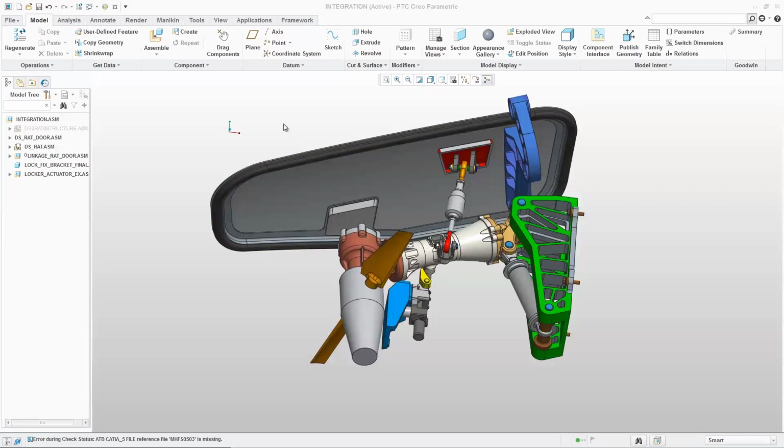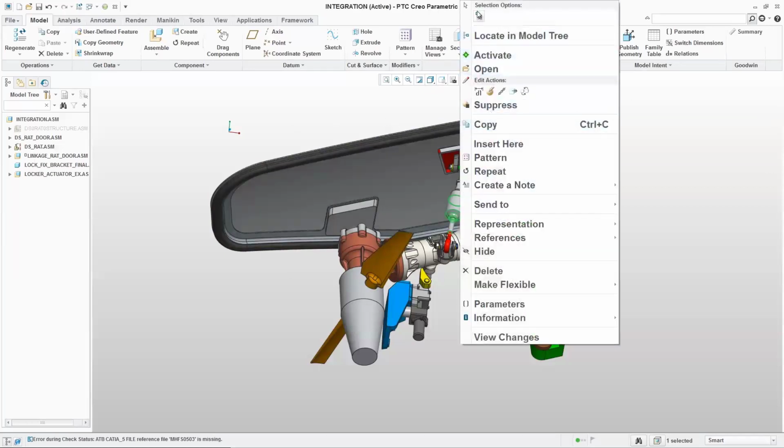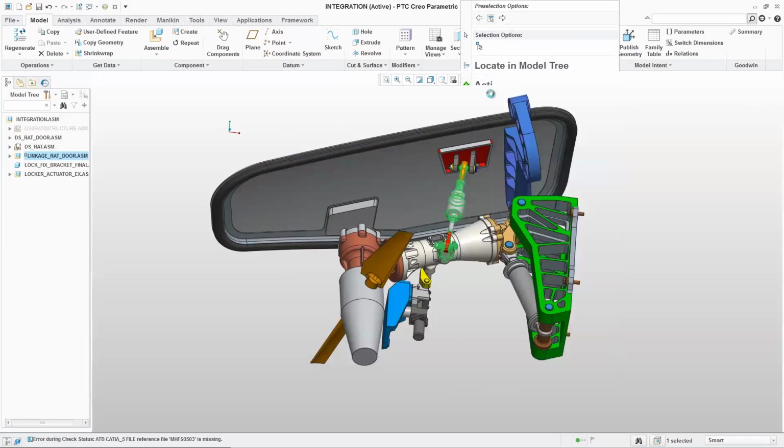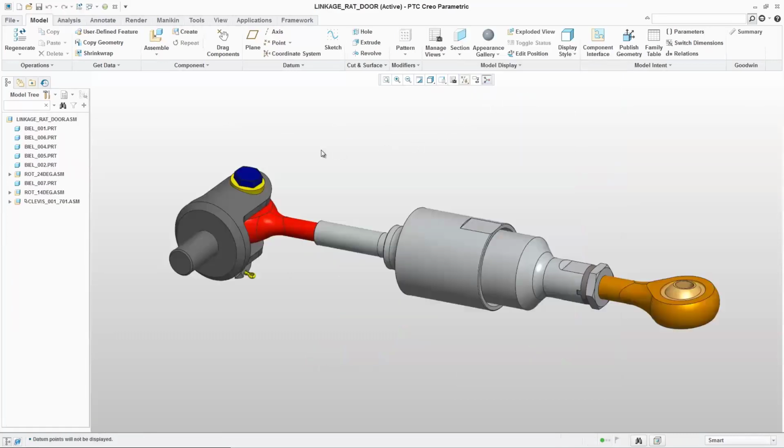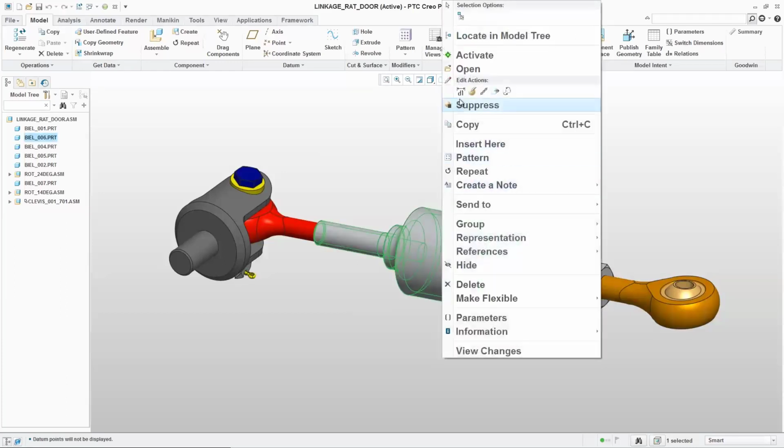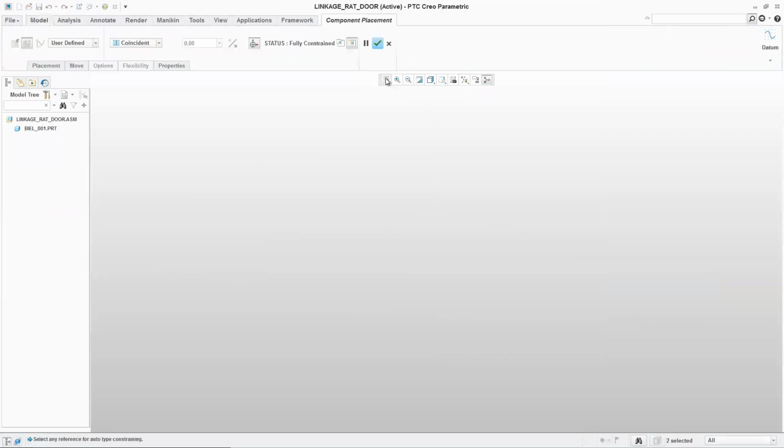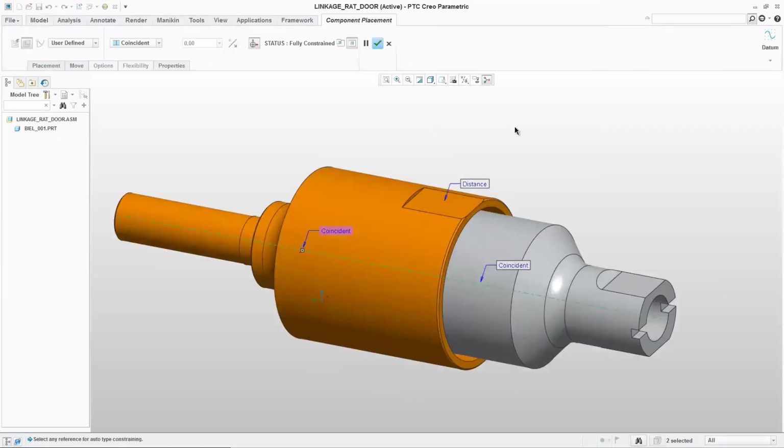In our case, let's say that we're starting on one of the linkages on that turbine. And that linkage in and of itself is a hydraulic dampening linkage. Traditionally, how you would assemble this if you're not considering mechanisms is you would do a coincident in the middle, align maybe the flats together, even align the outside. And what this means is that you have all of these parts stuck together. You may be able to even put some distance to it.